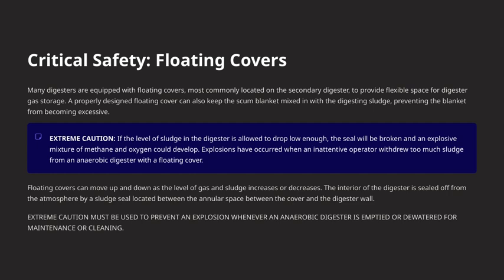Finally, I want to emphasize that extreme caution must be exercised whenever an anaerobic digester is emptied or dewatered, whether for maintenance or cleaning. This is a critical safety step to prevent any risk of explosion. Always follow safety protocols carefully when working with these systems.